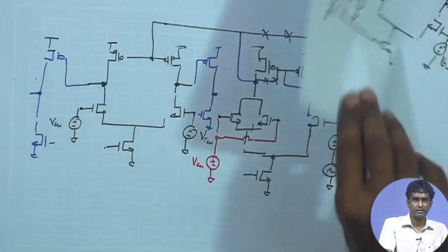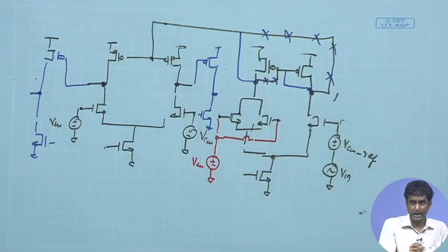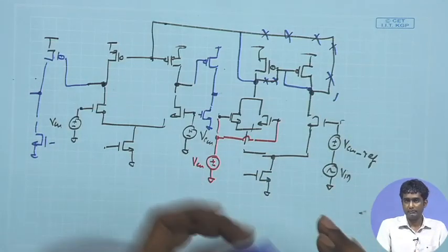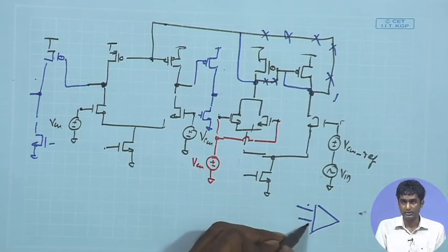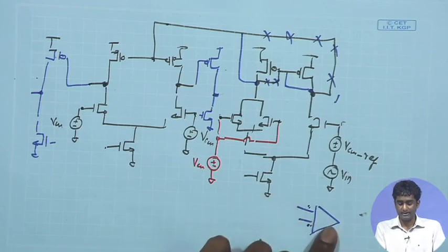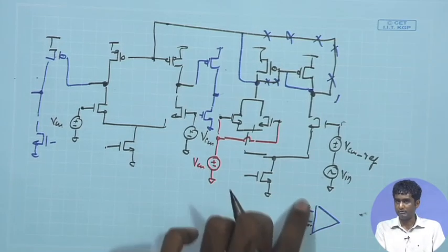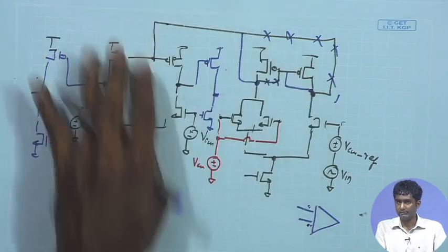In the negative feedback, eventually it will not be exactly the same. It will have some error, because remember in the negative feedback, what do we assume? If there is an error amplifier, we assume that once you connect it in negative feedback, these two are exactly the same, but that does not happen, because if there is a finite gain amplifier, there will be some minute difference between these two inputs, and that is ensured by the negative feedback.